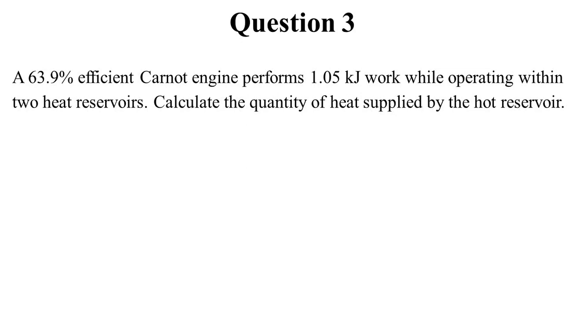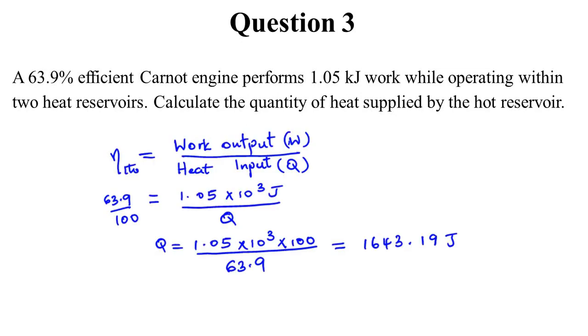So basically, if you understand the Carnot cycle, efficiency is one of the most important aspects when you talk about these engines that work with the principles of the Carnot cycle, doing work by supplying heat. So here we want to use a simple equation where we say that thermal efficiency, that's why we write η_th, equals work output over the heat input. There are other formulas for this, but this is what is more relevant to us.